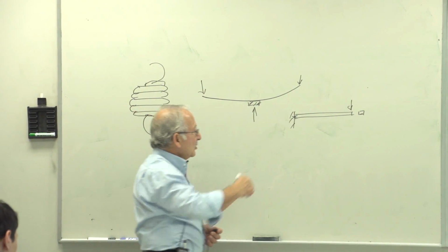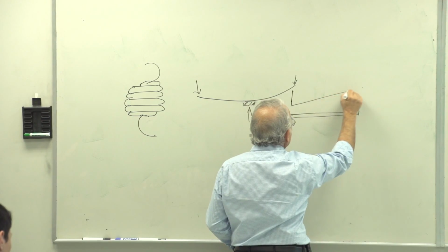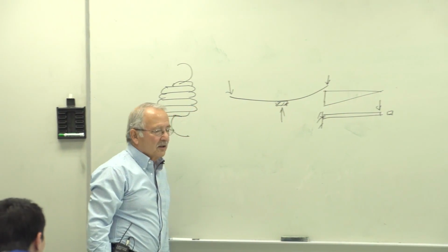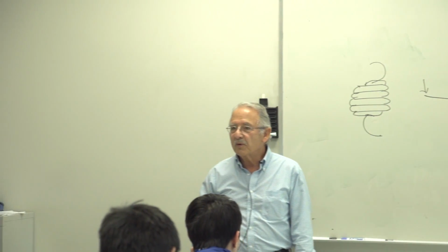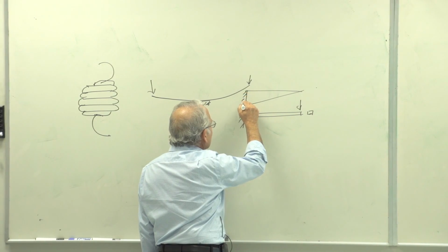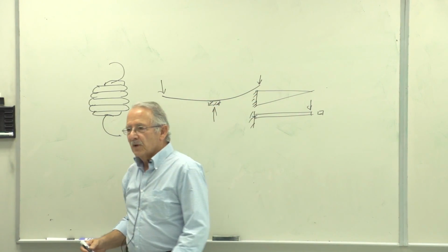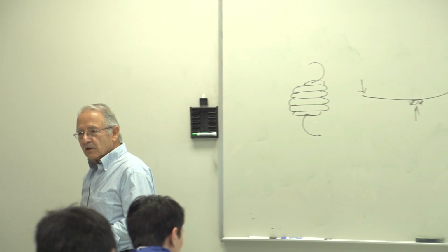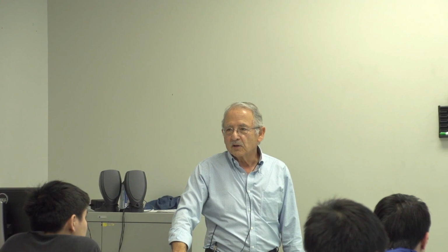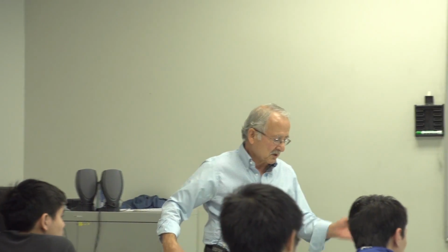But if you look at the spring from the top and you see something like this, in other words, the surface on top is a triangle. So this is your fixed end. And the force is applied like that. So you can design that spring so that the stress will be constant due to the applied load all over the spring. No maximum stress, minimum stress, same stress all over.